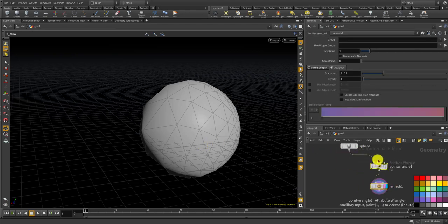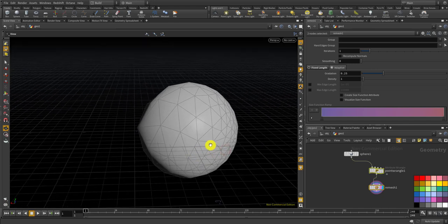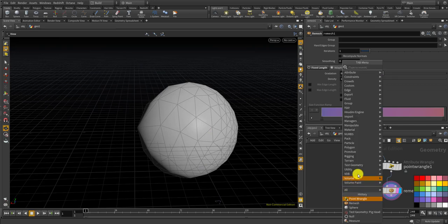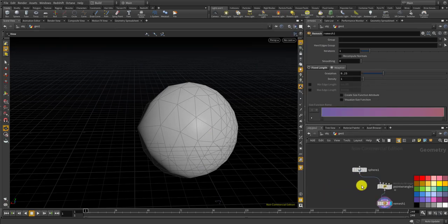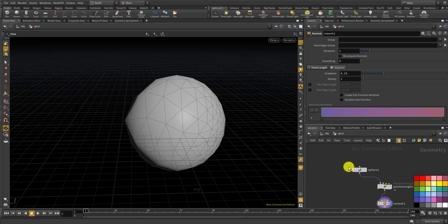Let's use this method to actually remesh depending on the value of the curvature of the mesh. So high curvature places have more divisions, remeshing, and low curvature places have less remeshing. Now in order to make a geometry with various curvatures, I would like to use a metaball.